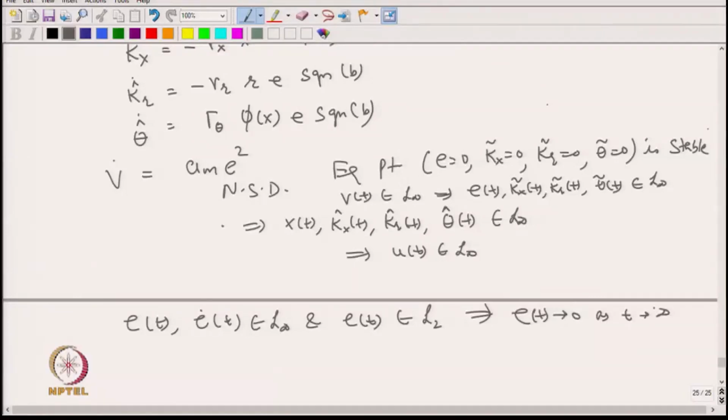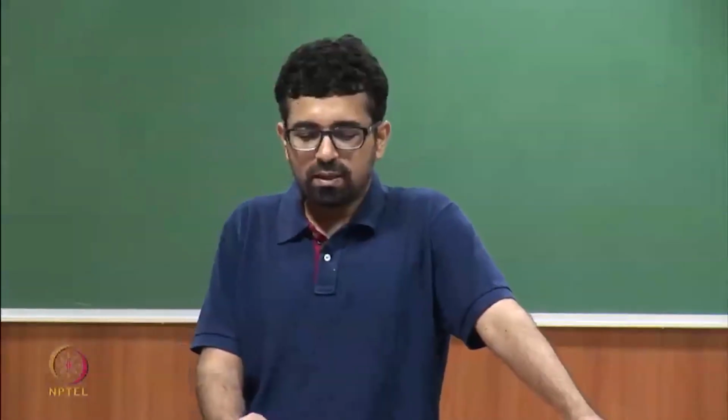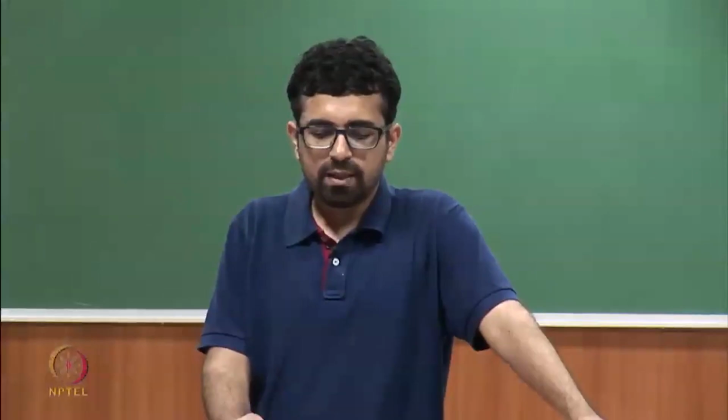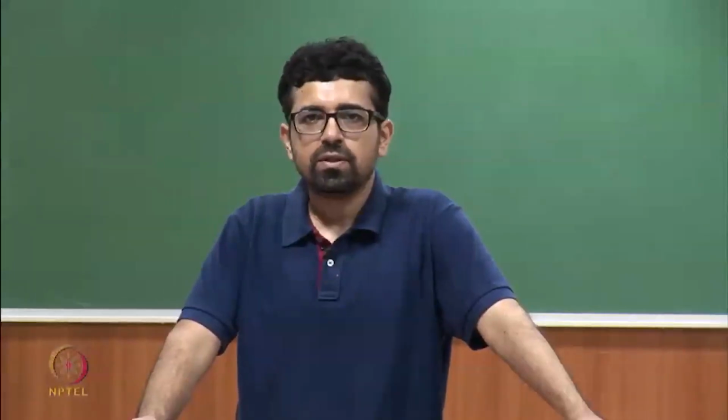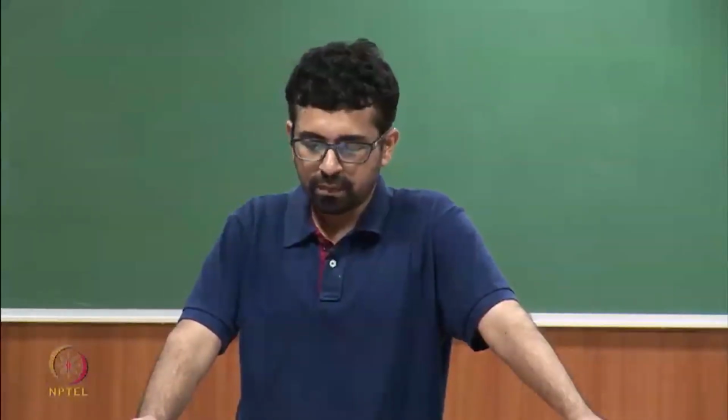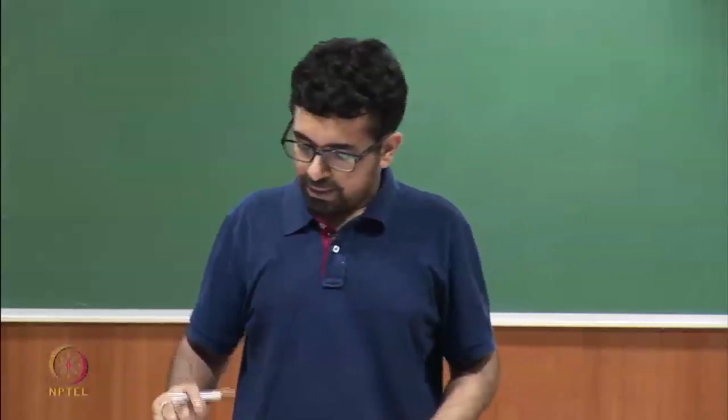So again, in this case we have been able to prove that the tracking error converges to 0, although the same cannot be said about the parameter estimation errors. All we can say about the parameter estimation errors is that they are bounded. In many cases, this is all we need. Our most important objective is for the tracking error to go to 0.